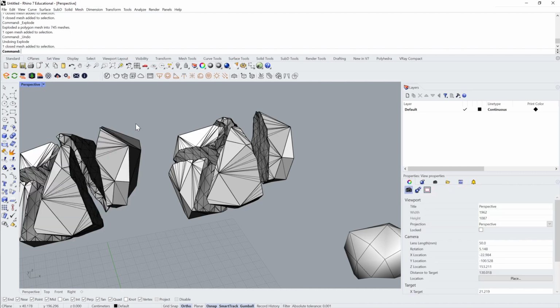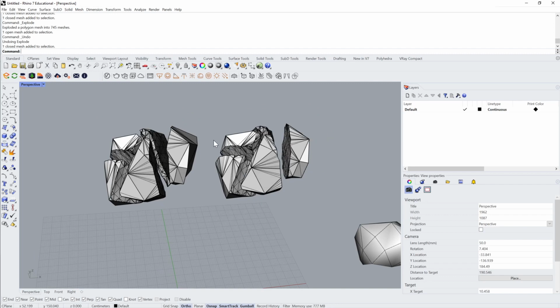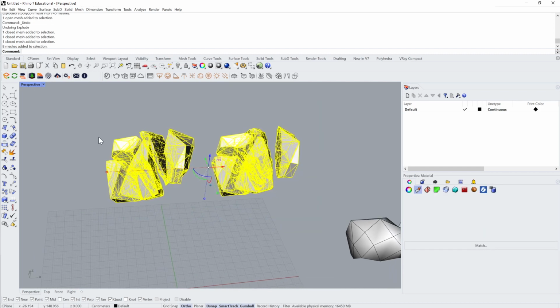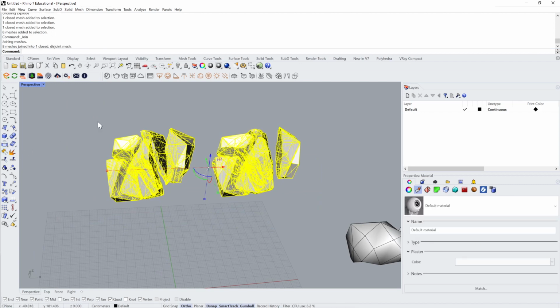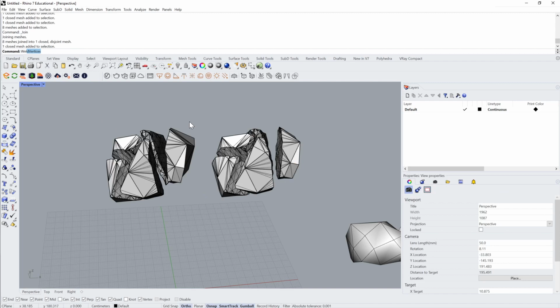So how would we do that same merge operation in Rhino? Well, let's just select both of them and join them. And that makes them one mesh. Now we want to weld vertices, and weld vertices is the command. So this is like Rhino's version of the merge command.